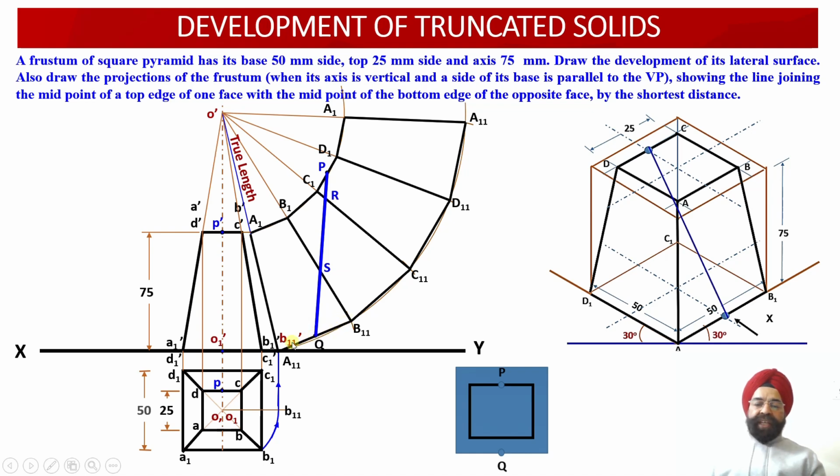So if we project it back, we find that into the apparent shape projections, that is the front view projections over here, the point Q dash will be lying at the midpoint of the base edge A1 dash and B1 dash over here. We can check this point happens to be A1 dash, this point happens to be B1 dash. So at the midpoint of A1 dash and B1 dash, we have located the point Q dash over here in the front view projection.